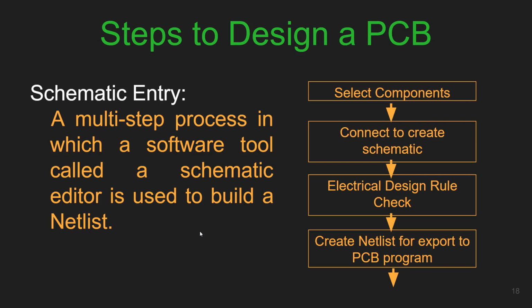Now, what is schematic entry? It is basically a multi-step process in which a software tool called a schematic editor is used to build a netlist. The schematic editor you will see on the top of your screen when you use the KiCad software. And if you click on that, you can select the component and start building up the schematic. Here it says it's used to build a netlist.